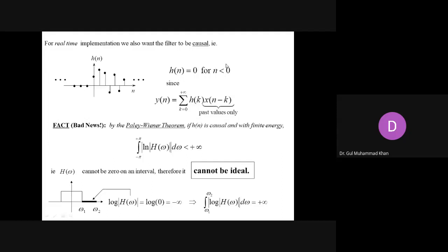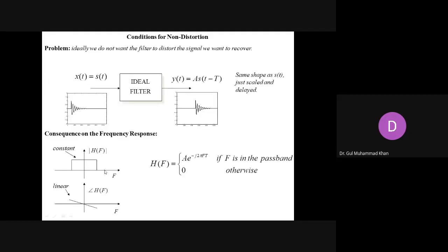Okay, so one more thing you have to keep in mind. The ideal filter response is supposed to be sharp like this, and it should have a linear phase. What do we mean by linear phase? Why is linear phase important? Linear phase is important in the sense that if I pass multiple signal frequencies to the system, they should be delayed linearly with respect to frequency. Based on the frequency, it should be delayed by that amount so that it is linearly distributed across them. Otherwise, the shape of the output signal is going to be different. And we all know that the information is always stored in the shape of the signal. It's not in the values. The variation is important. So the ideal response is supposed to look like this, and the ideal phase response is supposed to be linear always. So you have to look for these two things in any filter.